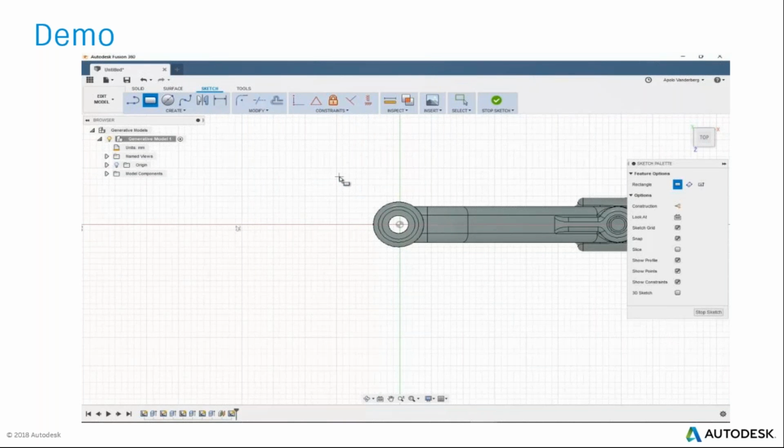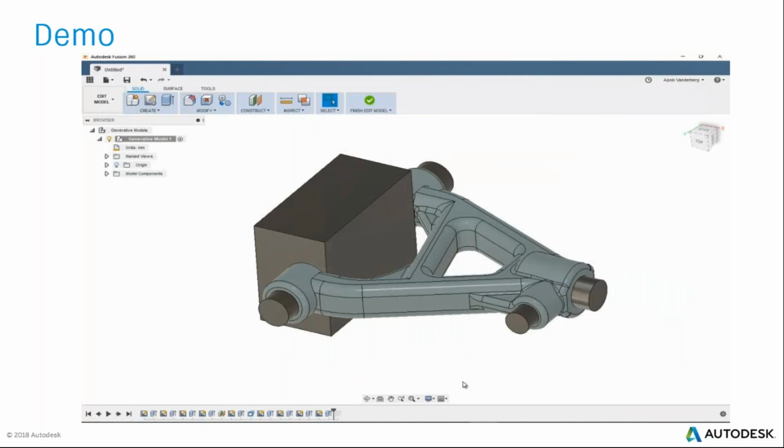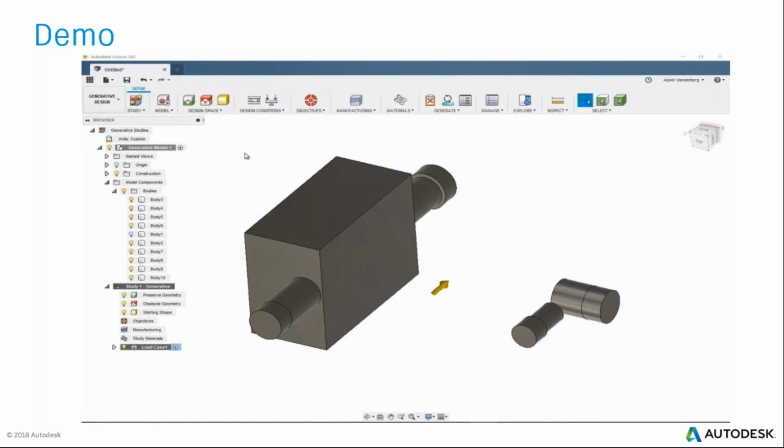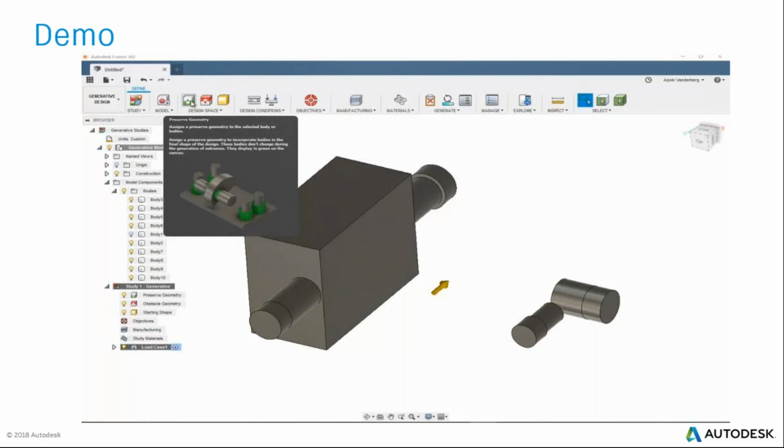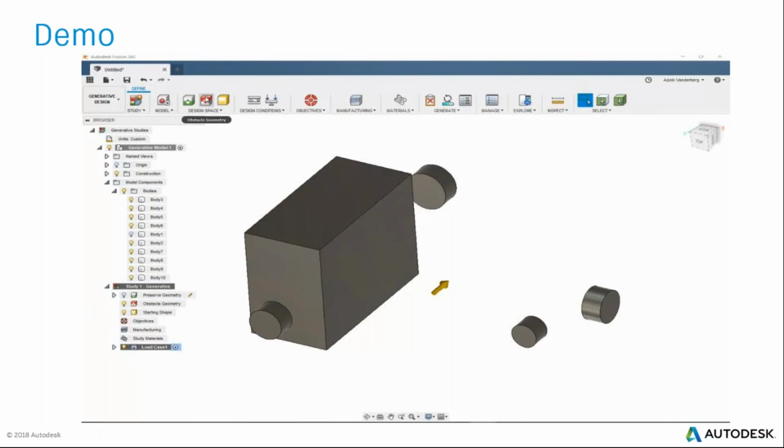If you want to change the relative orientation, so if you're looking at orienting this part for additive, you might have to change that location in your model prior to generating the outcome. So if you wanted a self-supporting structure at some obscure angle relative to the planes, you would have to set that up in the setup process. But that's a good question.